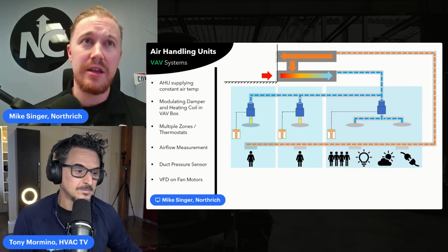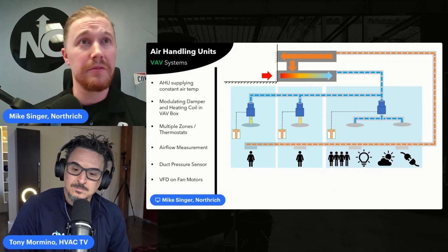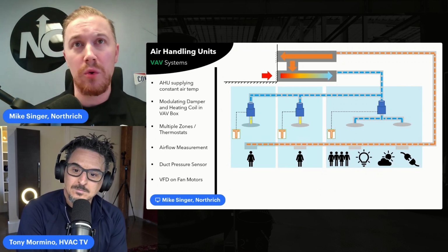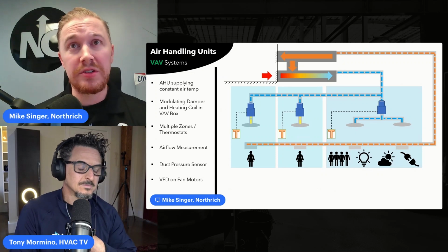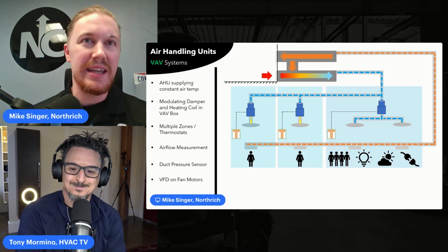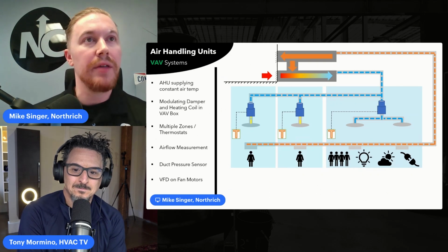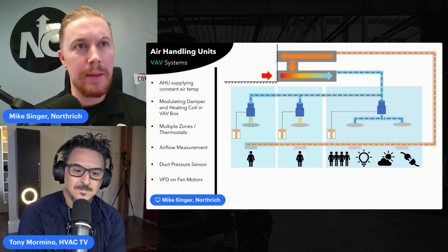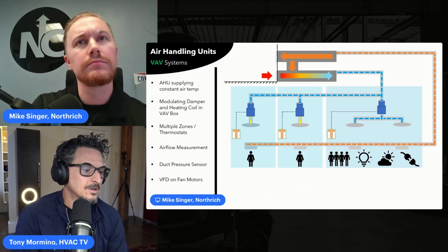If we want to dehumidify, maybe we're dropping down to 52, 53 degrees off of the coil, catching some reheat on the fan motors, and then obviously, like you're saying, reheating at our boxes to maybe 95 degrees to then provide the heat to the space. Yeah, that's great.